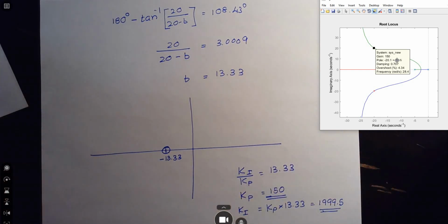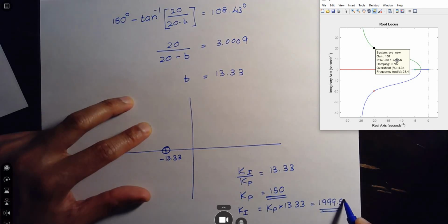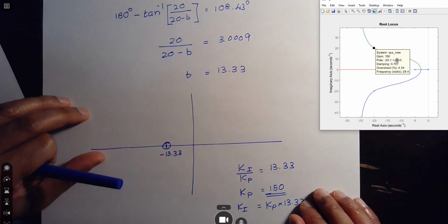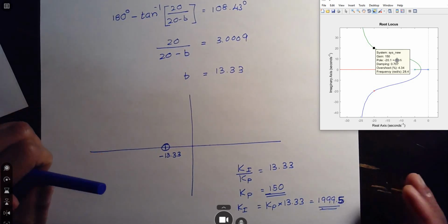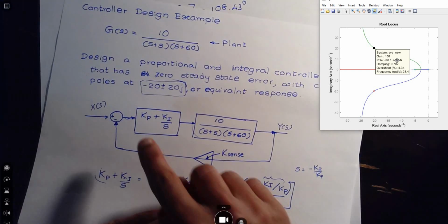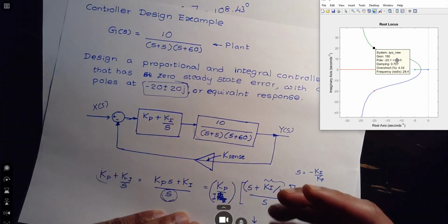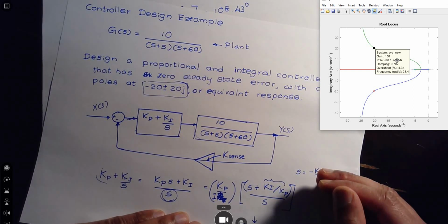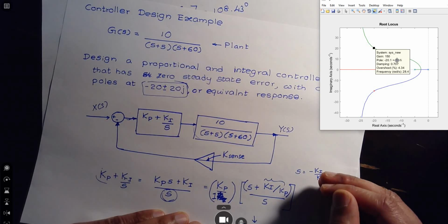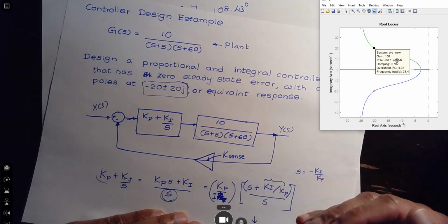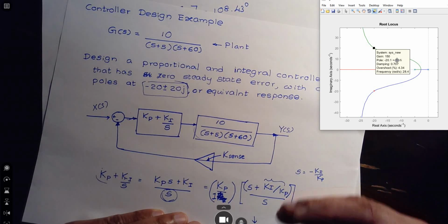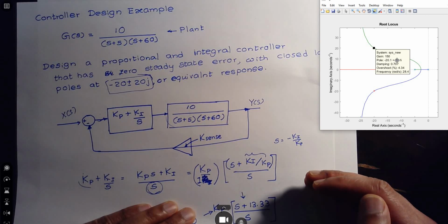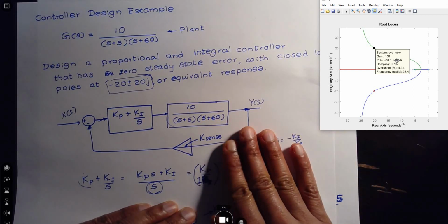Otherwise, all of you should be able to get this to work, and then you can implement your controller in Simulink, in the form of those KP and KI values in your original block diagram, and your closed loop response should match. When you inject a transient, a load change, your response again should match and still have zero steady state error, because that's what we designed the system for.